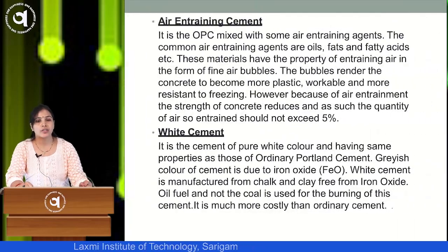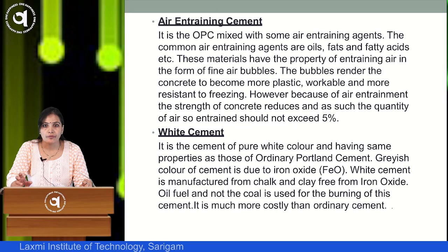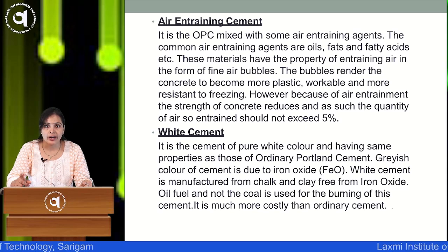Air entraining agents: this is OPC mixed with some air entraining agents. The common air entraining agents are oil, fats and fatty acids, etc. So, this OPC, ordinary Portland cement, we are mixing with some air entraining agent. What are the air entraining agents? Oil, fats and fatty acids.